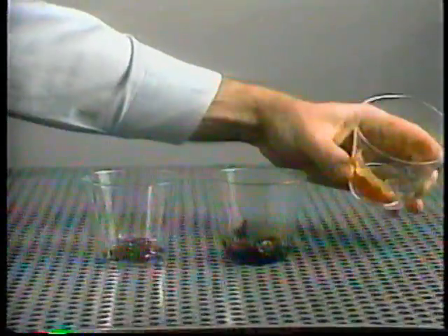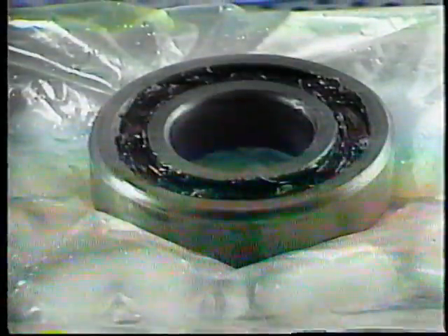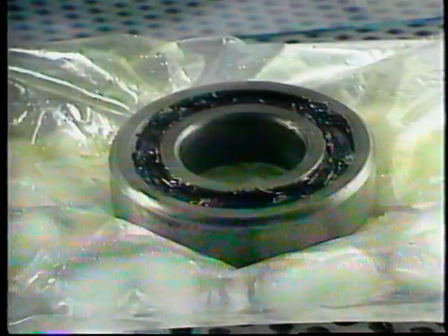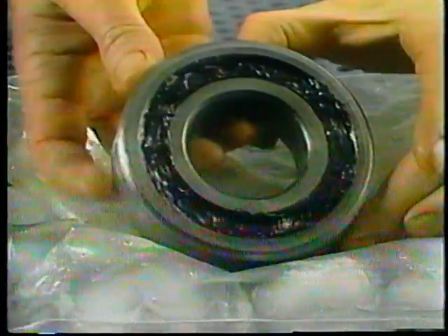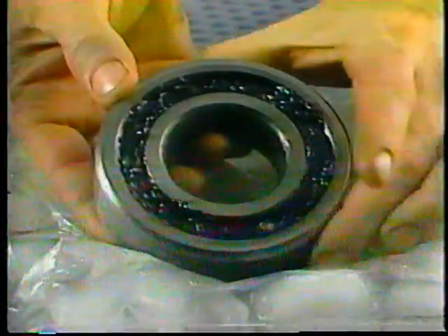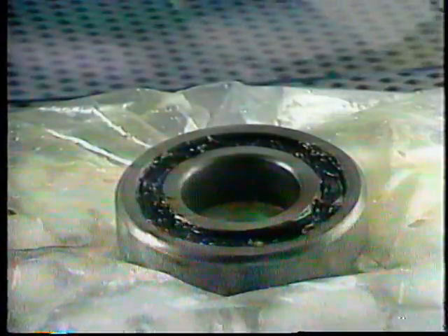The consistency of grease is measured in terms of its stiffness. Stiffness varies from 000, which is semi-fluid and almost like a heavy oil, to number 6, which is very stiff, almost like soap. Just as temperature affects the viscosity of oil, it also affects the stiffness of grease. At low temperatures, the oil in a grease may become so viscous or thick that it cannot flow well enough to provide a lubricating film.